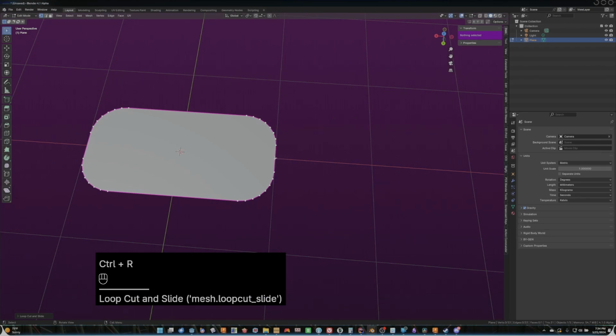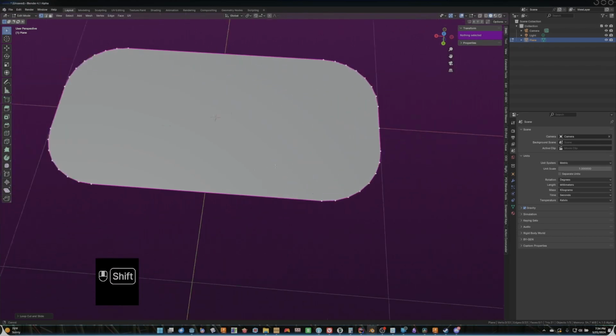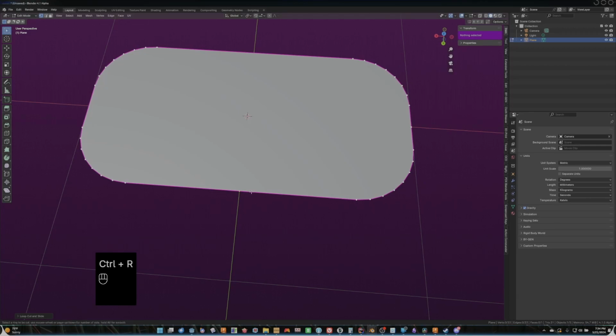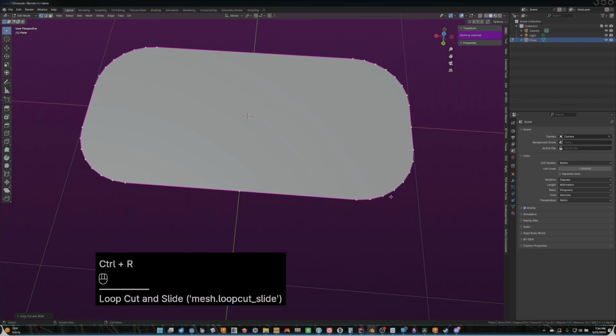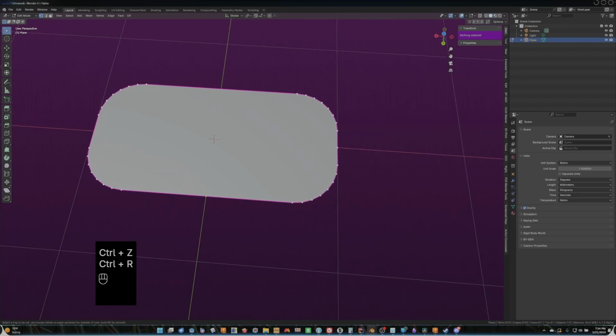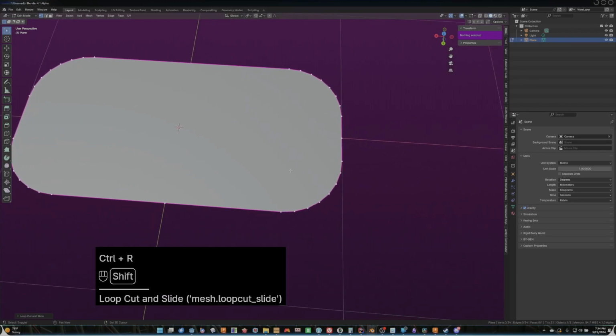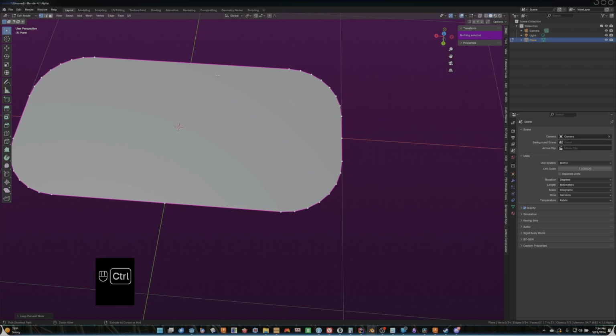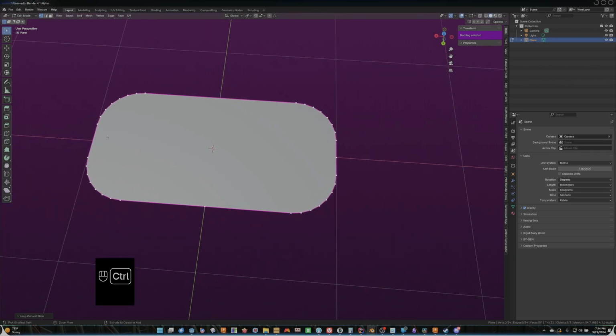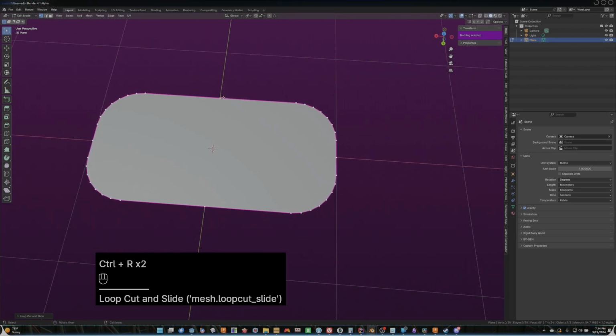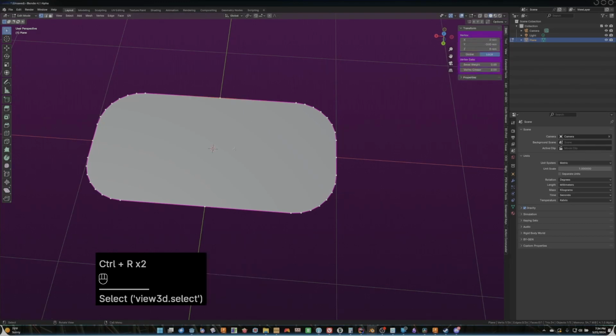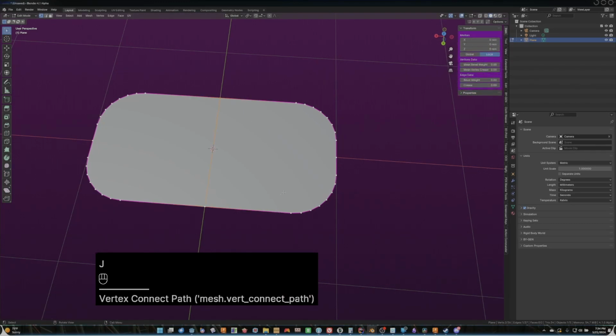I'm going to Control R and put a vertex on an edge. Now, anytime you have a non-manifold edge like that, that is, it doesn't have proper geometry, it's just going to give you a single vertex in the middle of that edge. And that's one good way to find the middle of an edge. It can be challenging sometimes to line up the middle of edges in Fusion 360, especially because Fusion 360 is horribly non-performant for complex geometry.